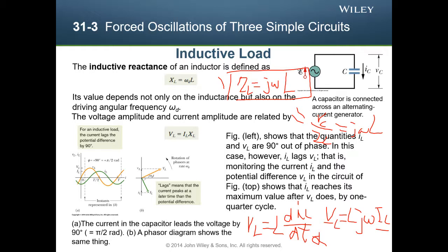But if we have multiple frequencies for this circuit, then you can use superposition. You can calculate for frequency 1 and frequency 2 independently, and then you add them together. That is because the phasor depends on the frequency, omega is 2 pi f, which is related to the frequency. So with multiple frequencies, you need to separate them, and then you calculate one by one.